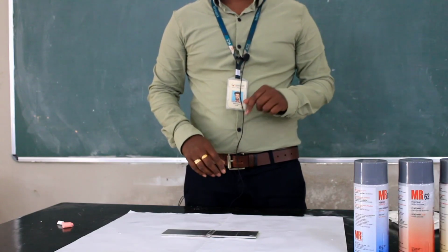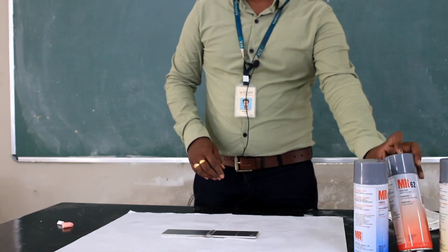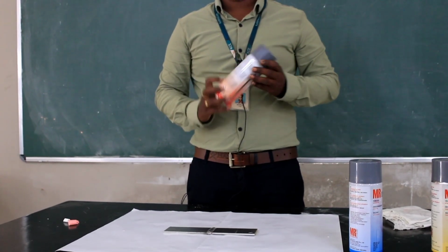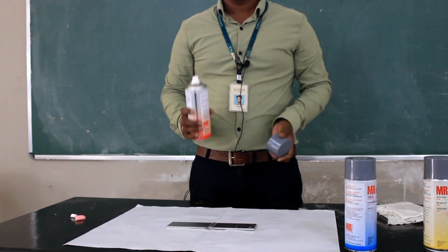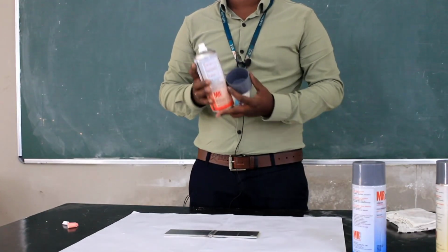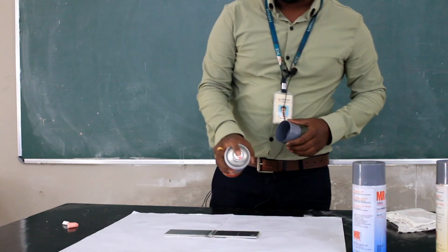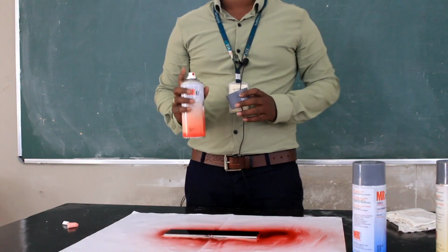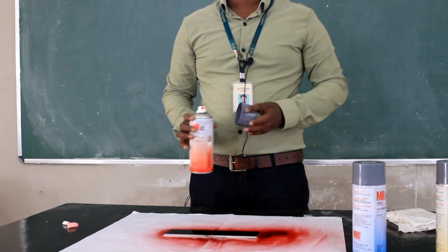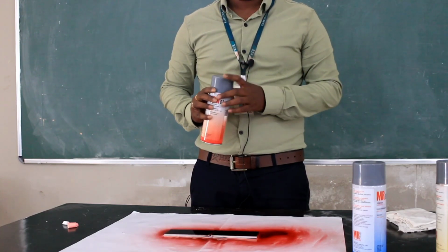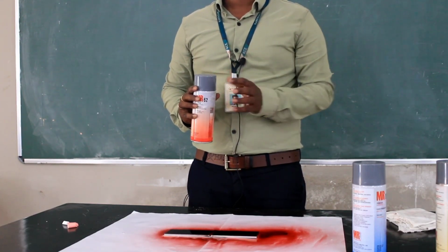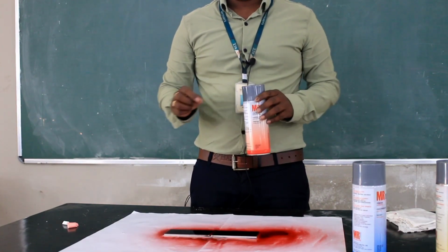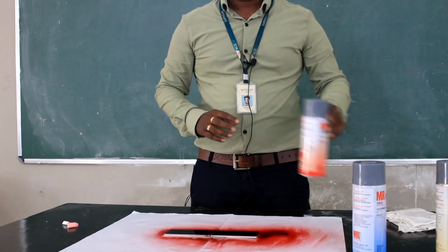The second stage of liquid penetrant testing is applying the penetrant. After applying the remover, we have cleaned all the dust particles. Then we have to apply the penetrant, which will settle into the surface of the welded sample. So I have taken the penetrant and I am applying it on the welded sample. Just one pass is required. We need not go over it a number of times, because multiple layers will form unwanted particles. Then we have to wait a minimum of 8 to 10 minutes. This time period is called dwell time.